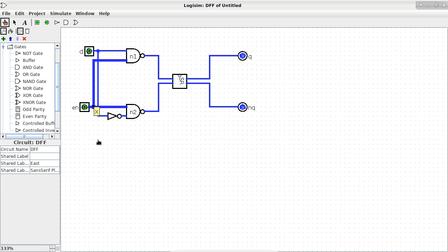1, right? Exactly. Okay, so can someone remind me again what happens when both inputs of an SR latch are 1s? Maintain state, do not do anything, right? Okay, so that means when En is a 0, nothing can happen to the SR latch. You can flip the data pin as much as you want, but nothing is going to happen to the SR latch. Whatever it was, it will maintain. Is that good so far?